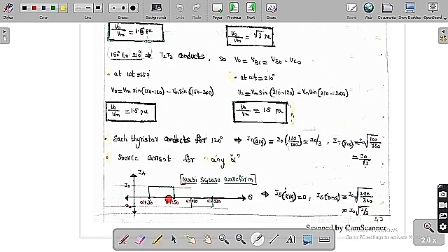So basically, T1 is conducting from only 30 plus alpha to 150 plus alpha. I have already told you. Whereas T4 is conducting from 210 plus alpha to 330 plus alpha. So this is the range of conduction of T1 and T4.